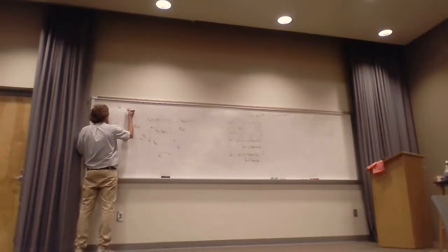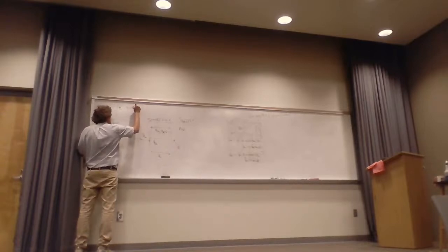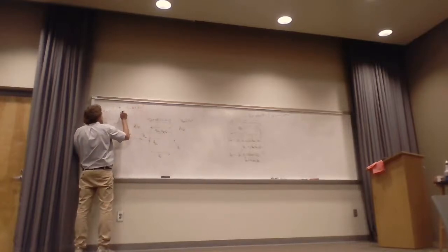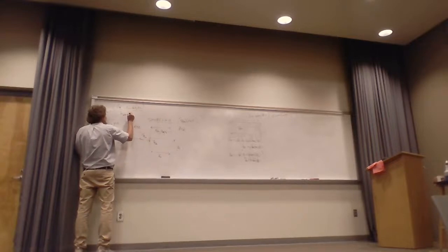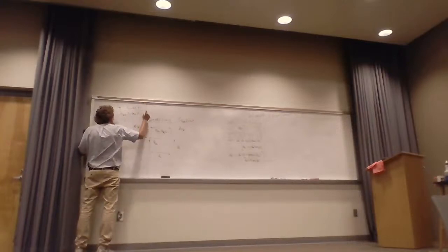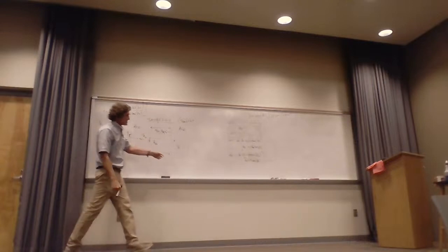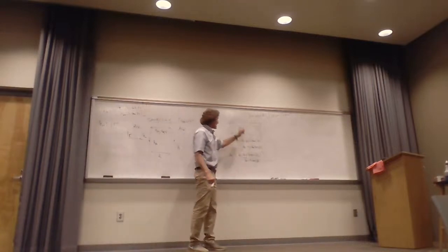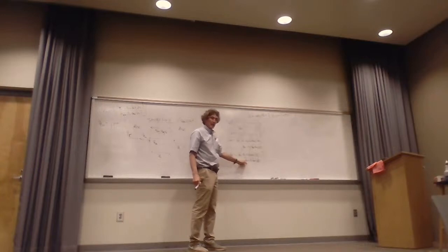And there's not a plus j, it's going to be plus, and then it would be eta of the shield times the hyperbolic tangent of gamma times L over eta of the shield plus eta naught times the hyperbolic tangent of gamma L. Now you'll notice this parallels this entirely because the shield here will be lossy, right?